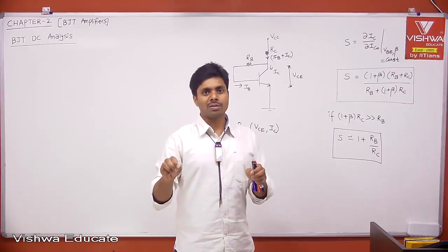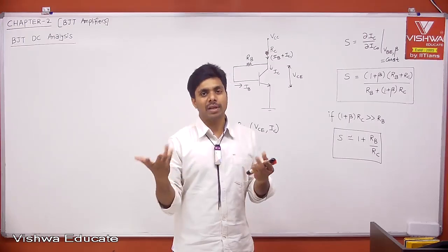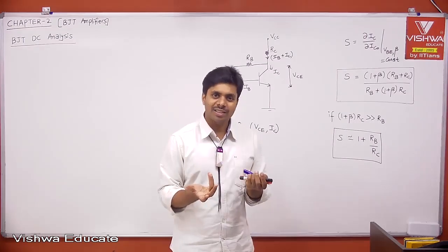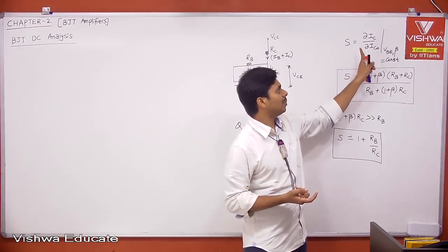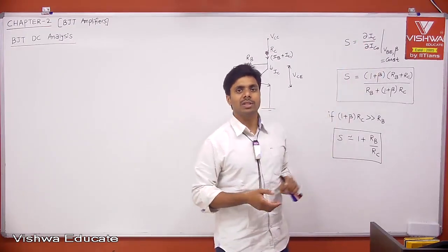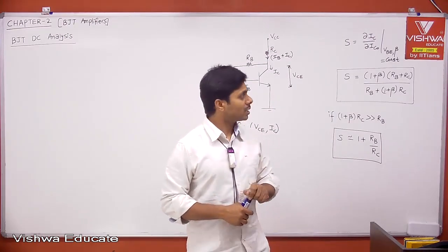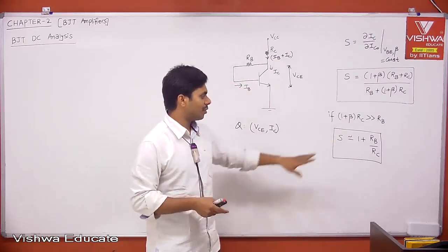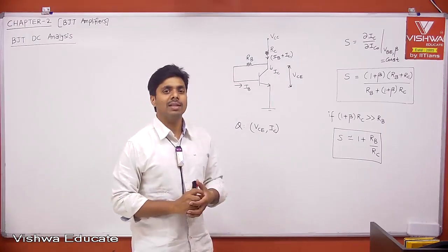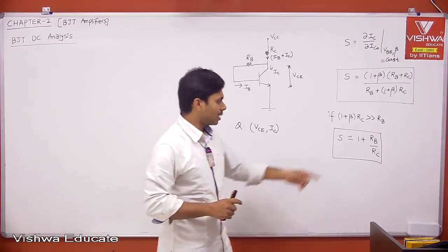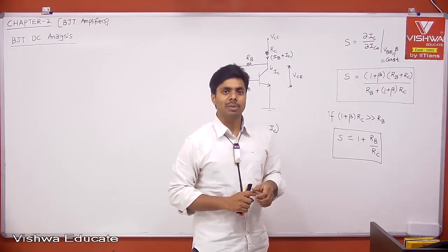Therefore, if it is a wire, V0 is equal to Vi, but your output DC voltage, what you are getting from input DC voltage, is independent of temperature, obviously, right? Therefore, we are speaking about stability factor to be minimum where my output current is independent of reverse saturation current, which is ultimately what is changing the Q point. Therefore, I want to have the Q point to be stable. To have Q point stability, RB is equal to 0, therefore you will get minimum S value. If RB is equal to 0, your AC gain is affected. Your AC gain becomes less than or equal to 1. Therefore, that is not the practical solution. Mathematically, it is giving a solution, but it is not giving you a practical implementation.